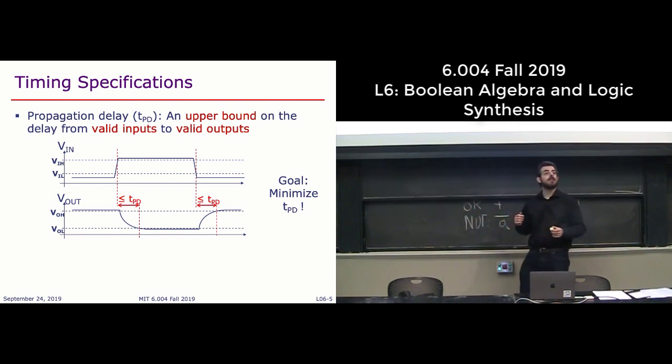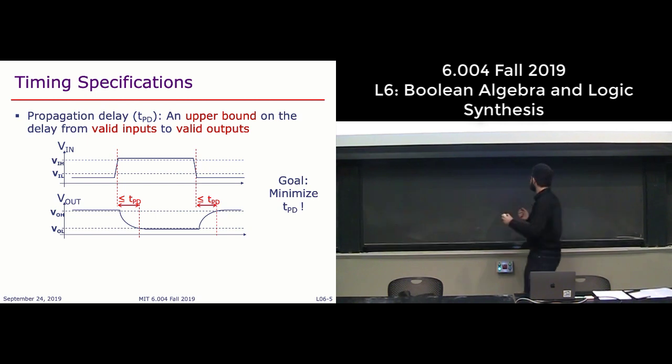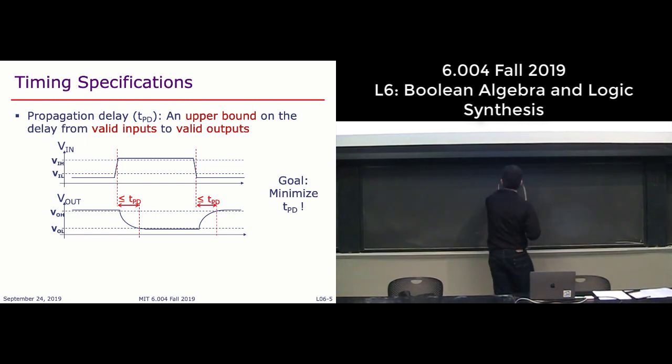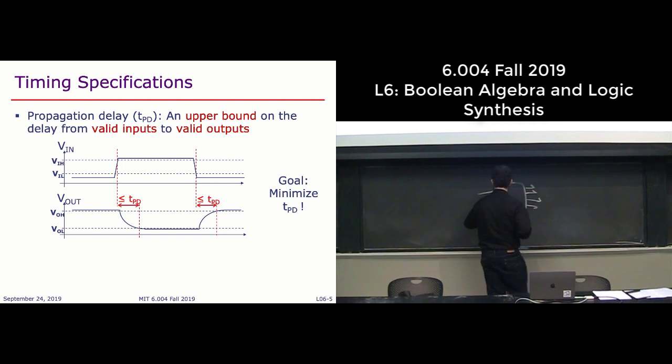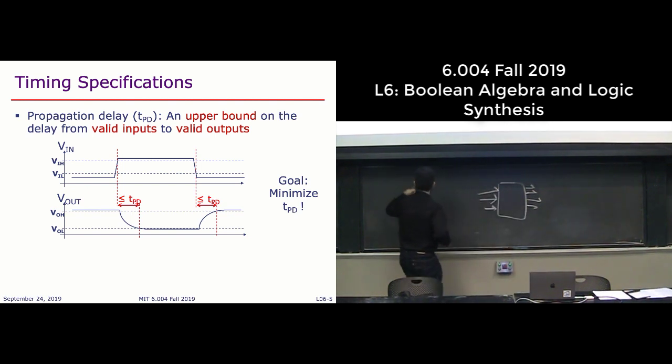The way it's going to work is through what we call synchronous sequential logic. And so we're going to sandwich this combinational device. It's going to have multiple inputs, it's going to have multiple outputs. And so if we have what we call a clock frequency of, let's say, 1 gigahertz, that translates to a clock period of 1 nanosecond.